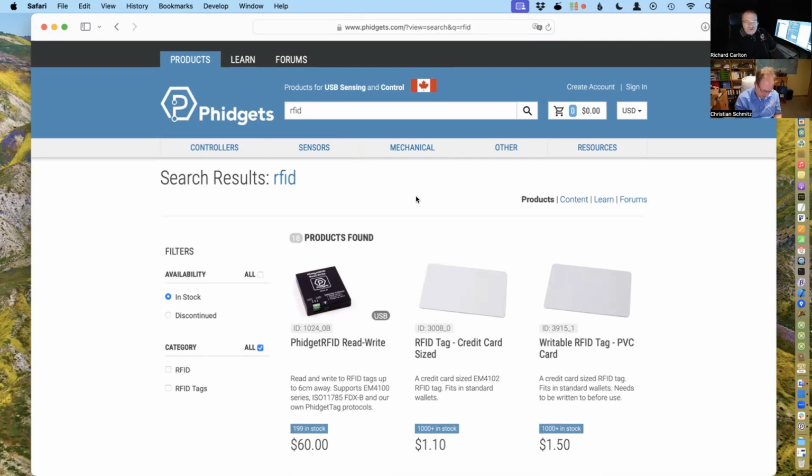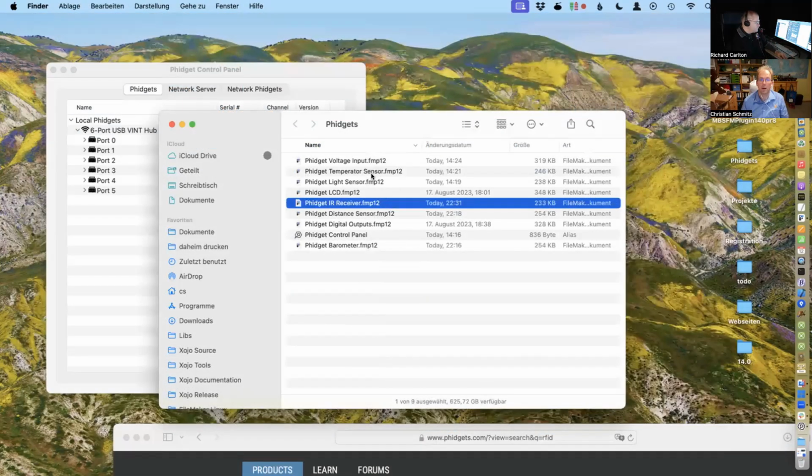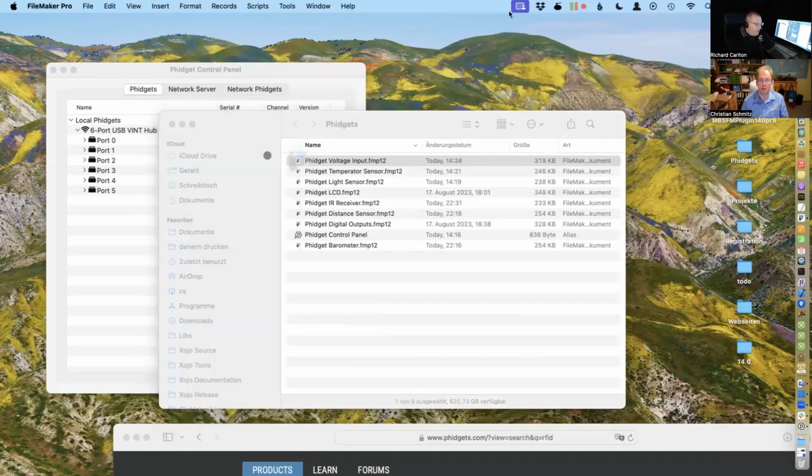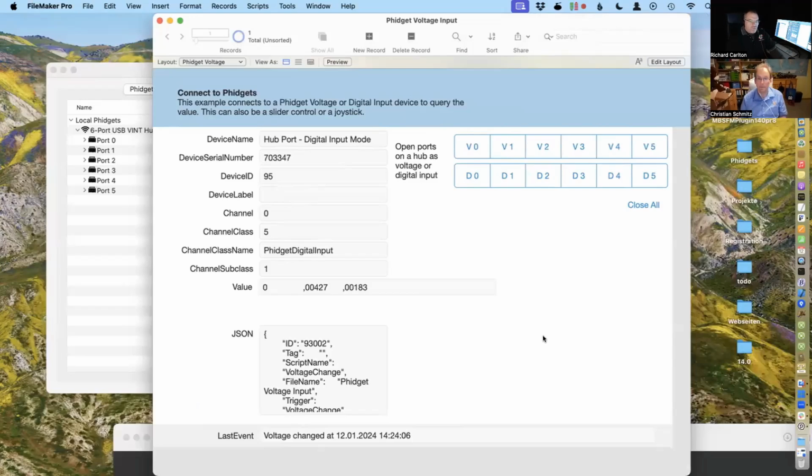So now let's just try the joystick. It's basically a digital input and an analog input for two axes. Let me connect it. I need more cable. So the hub has now connected the digital input from the button at port 0, and 1 and 2 are the axes. So I would say digital 0, and 1 and 2.